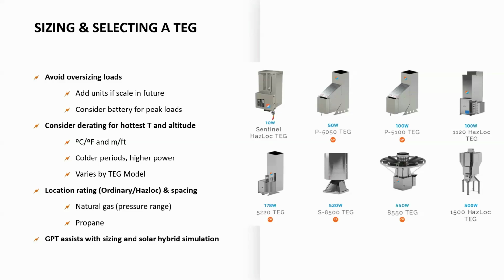The other situation in which location is really important is when you're doing the solar hybrid work. So you can also come to GPT and we can help you do a simulation. We have a software which will tell us how much solar radiance the location gets over the year. And then we can make sure that your TEG is not cycling on and off too frequently and that it's sized appropriately.